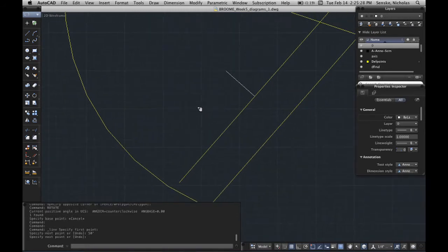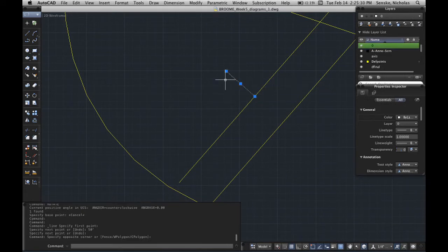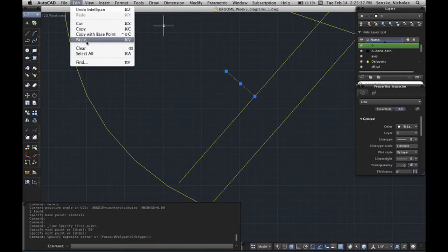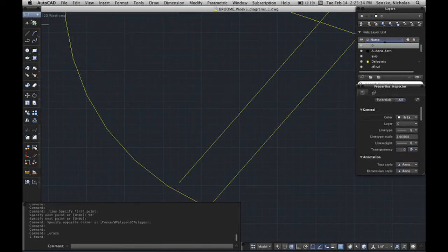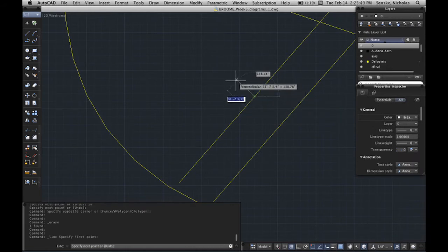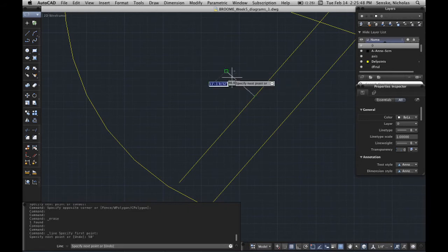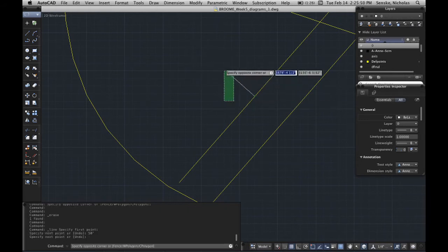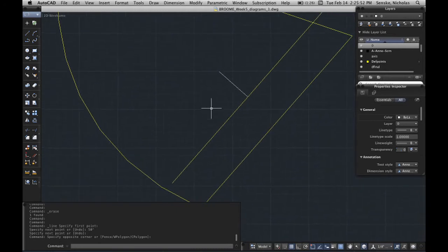Okay. Where did you get the perpendicular from? That's a command. If I start drawing a line, so I offset, it just kicks in. I offset it, and I have a point on that line, and I start the line there. As I'm drawing, if I'm close to it, it's going to snap to perpendicular. That's only if you have the dynamic input turned on. And then I can type in a specific length, and then I could begin to offset this in order to begin to establish the lines of it.